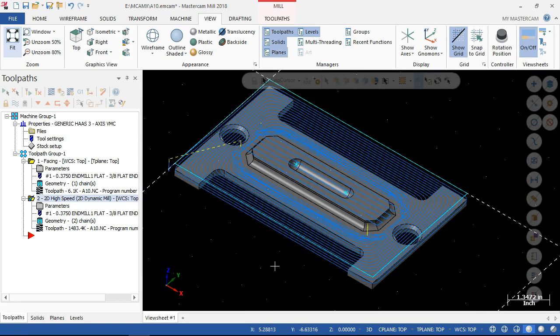All right, so it goes around the outside, and I think what I'm going to find is I get this to the machine and actually see it cutting. Even at the 4,000 RPM, I'm going to be able to bump this up to 24, 25 inches a minute, or instead of about 0.100 step over, maybe take it up to a third or 50% tool engagement.